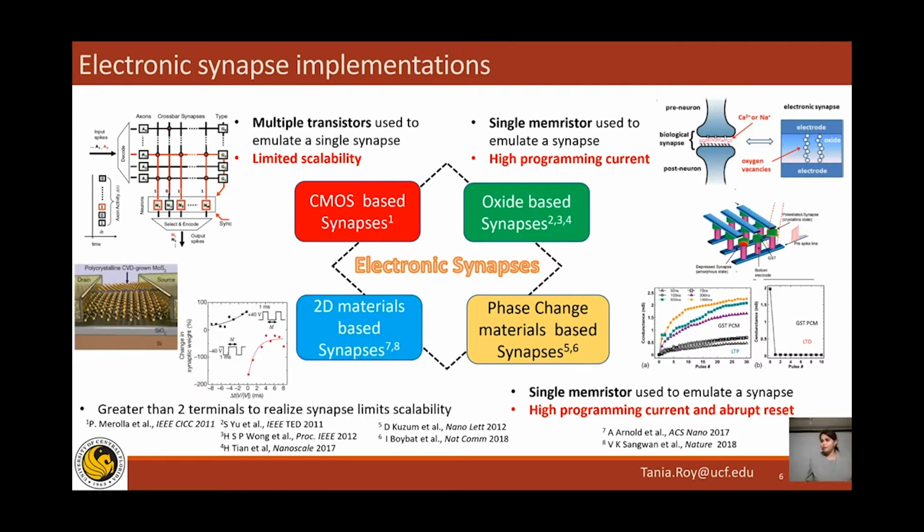Nowadays, 2D materials are being used to show these synapses. There's a lot of work shown here. It initially started with using a FET configuration, so a 3-terminal device was being used to realize the synapses. Because of the defects present, there was hysteresis that was being modified to multiple conductance states, similar to the floating gate effect. Other mechanisms of synapses were also shown in FET structures. Could be phase change, could be other mechanisms.